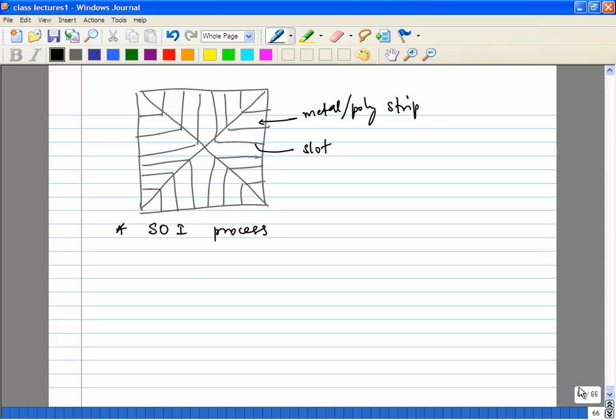So each case may have one ideal type of inductor you want to use, because the actual Q depends on so many other factors, the way you design the inductor. Then what did we do? We looked at, of course, the last figure of merit, which was the area. It comes down to cost; you can only afford to use a certain amount of area for your inductor.